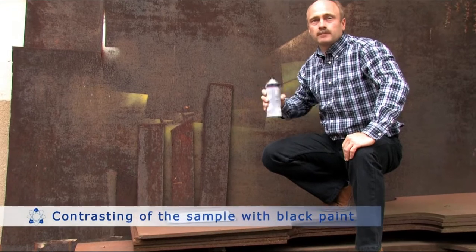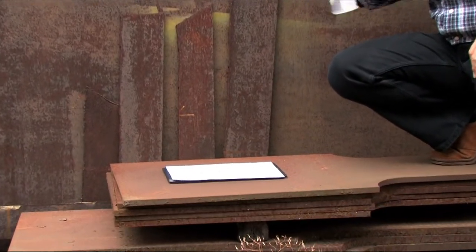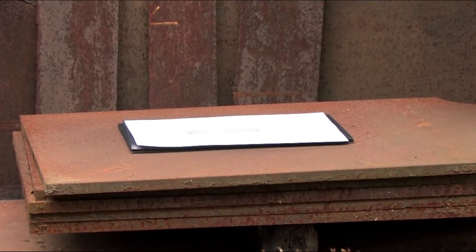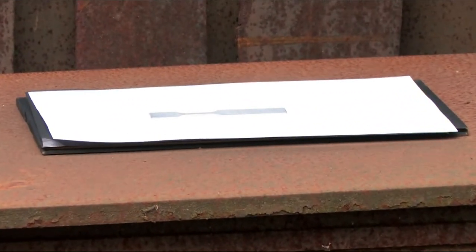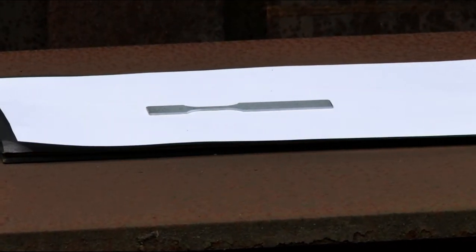Firstly, the sample is sprayed in black and afterwards the shoulders are painted in white. This color contrast is necessary because the strain is measured with an optoelectronic extensometer directly on the sample.